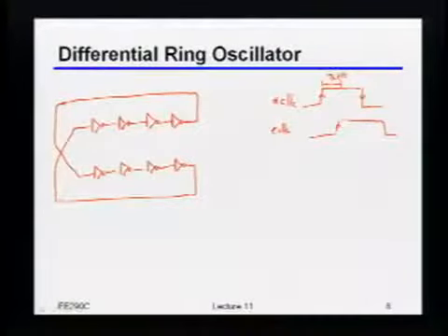Now there's just one quote-unquote minor caveat. So what's the minor caveat here? Is this guaranteed to work? How do you make sure that you start off with the inverters? How do you make sure that you start off actually with the bar of the signal on one side versus the other? It turns out you can actually ensure that. The way you ensure it is you literally just throw something in there that forces it to be that way. The most common way to do that is to add some cross-coupled inverters like this.